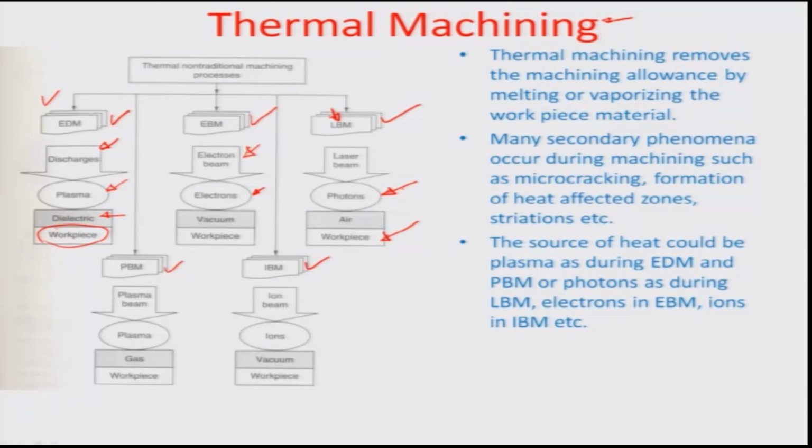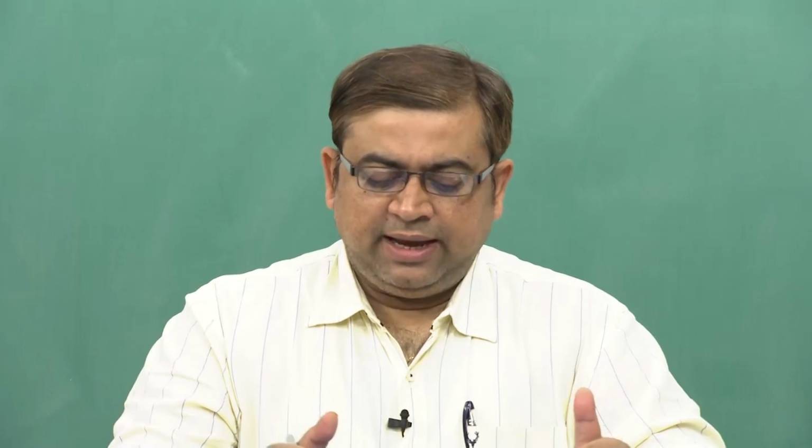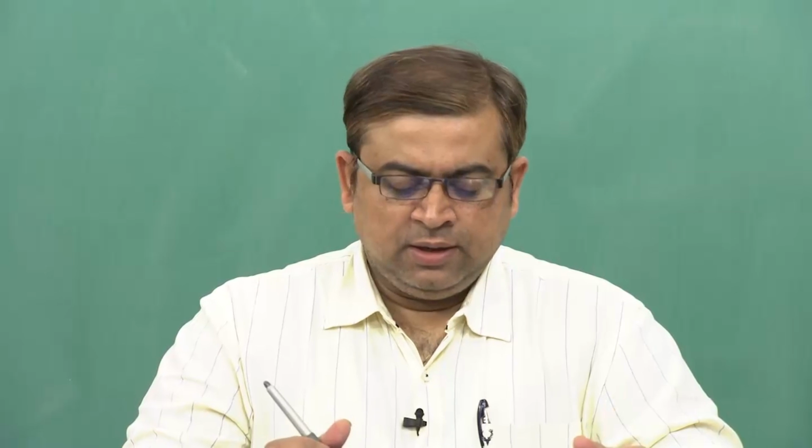Okay. So, the e-beam system deploys a vacuum which is actually a shortcoming of the process, which kind of limits the workpiece size, but in case of laser you can do this kind of machining over a very large or a wide area surface, and that is the reason why laser is used sometimes for wide area texturing and various other applications which you can think of in thermal machining.